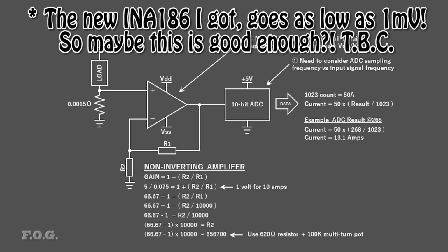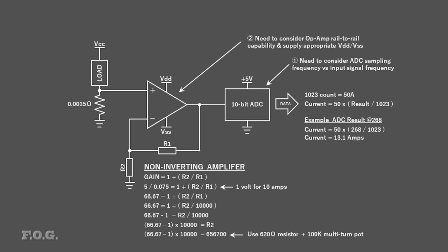Now for the final point, but likely the most important one of the bunch. So this method of current measurement is actually called low side current sensing. Obviously, because the sensing is done below the load, on the low side. But there's an inherent problem with this method. As we discussed, we expect a voltage drop across the shunt relative to the current, right? But this in turn means that the actual ground and the ground as seen by the load are not going to be one and the same thing, right? They're going to have some potential difference between the two, depending on what the load's doing.